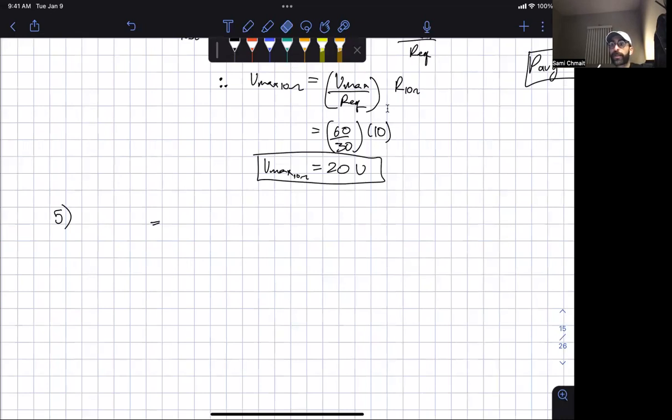What percent of power can be saved if we're using that step up, right? So it's delivered at 50,000 instead of at 12,000. We're asked a two-parter here, and we're going to need to do a percent difference calculation at the end. First, we want to know how much power is delivered through the wires, and then how much is lost through the wires. Then we're going to compare those two questions relative to each scenario.